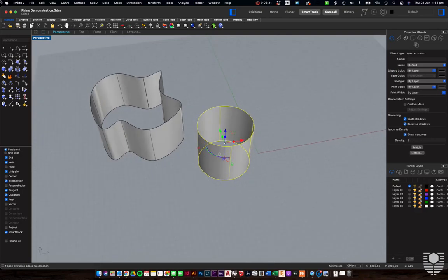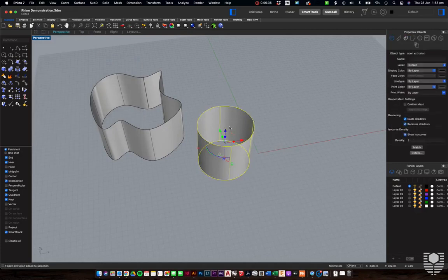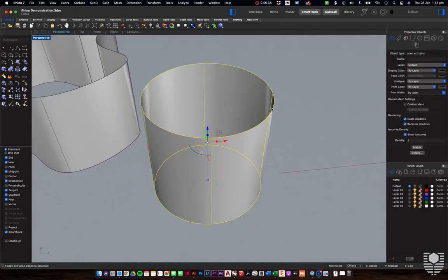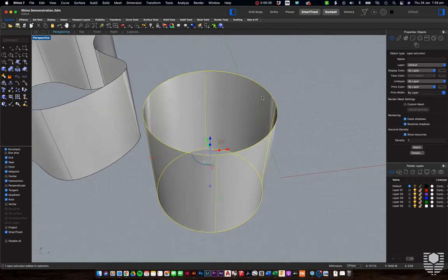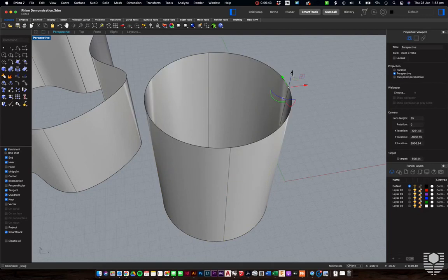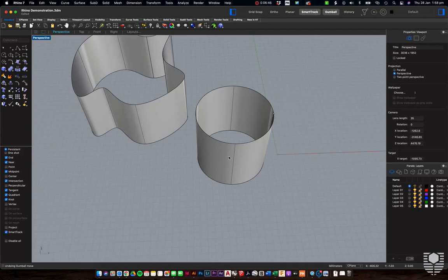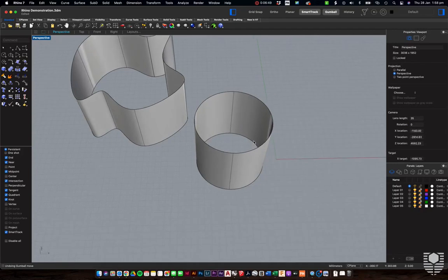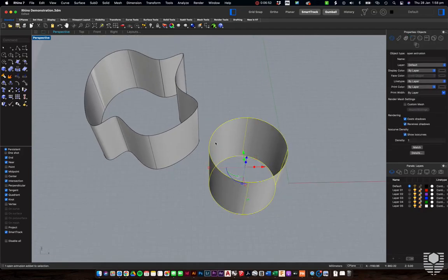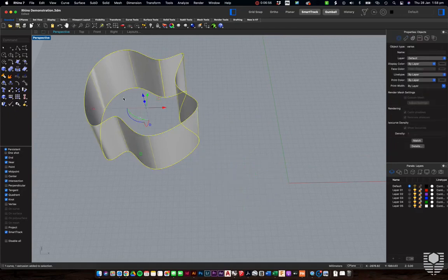If we then go up to our edit control points on, we'll see the difference between a complex surface like we were dealing with before with all those control points versus this, which is a lightweight surface. So now in this case, we only have these 2 points to manipulate, which you can see there. We've just got that one control point and the one that was down the bottom as well. So that's the difference between a complex and a lightweight. So more complexity will come by adding some more control points using the rebuild command, which we'll talk about a little bit more in a second.